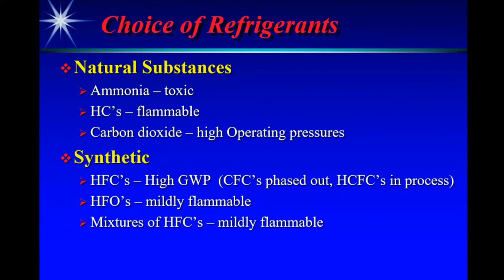The synthetic refrigerants which the human race have developed are now being questioned. Especially I mentioned the HFCs, which have high global warming potential, and the new ones are HFOs, where the global warming potential is very, very low, but they also have mild flammability concern. And a new class has been created in the recent times, which is called A2L, to handle these mildly flammable refrigerants. Even people are proposing mixtures of several refrigerants, and many of them are mildly flammable. So there are no clear-cut solutions which are readily available for most applications. And one has to have a trade-off and decide what is possible in a given scenario.